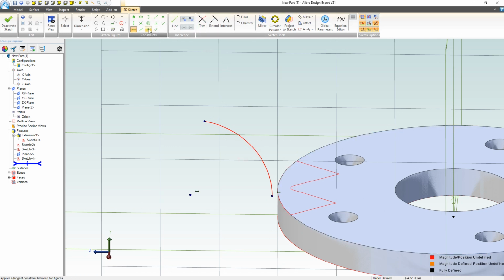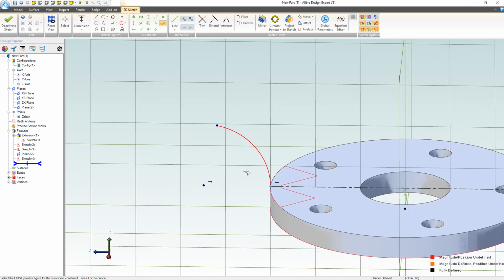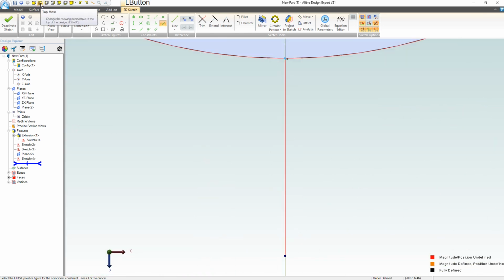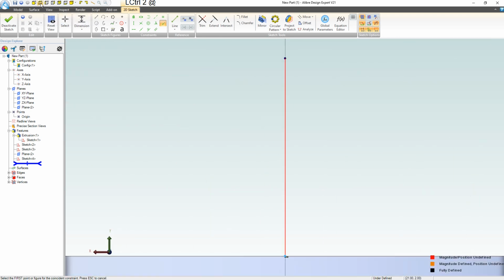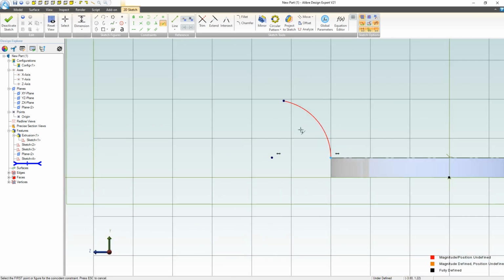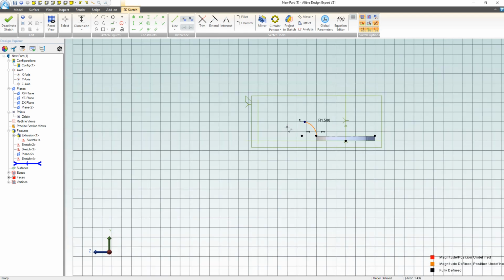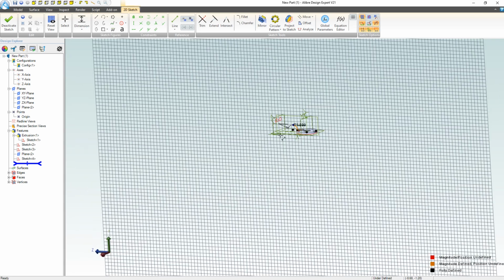And I accidentally added a constraint there. Of course I did. Let's add instead a coincident, right? Maybe even, yeah, right on that point. I like how it added that construction line for me automatically. That helped out. Let's see if the SolidWorks view hotkeys work here, control 1, yeah, they do, 2, 3, 4. So SolidWorks view control hotkeys are the same. That actually seems like a nice radius to initially come out with. Let's make that 1.5 just to be a nice even number. And then our other sketch is right there.